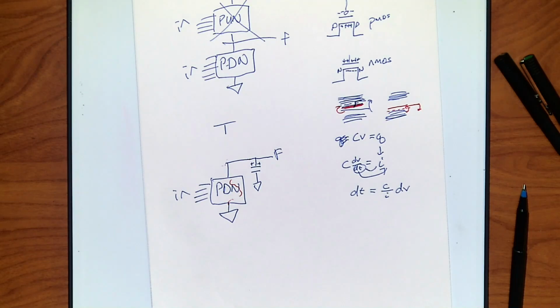So we're going to take our clock, and we're going to make basically an evaluate, don't evaluate period. Right? So we're going to have basically two cycles, a charging cycle and an evaluation cycle. And you have to do this across a clock period anyway, so this is no problem, right?